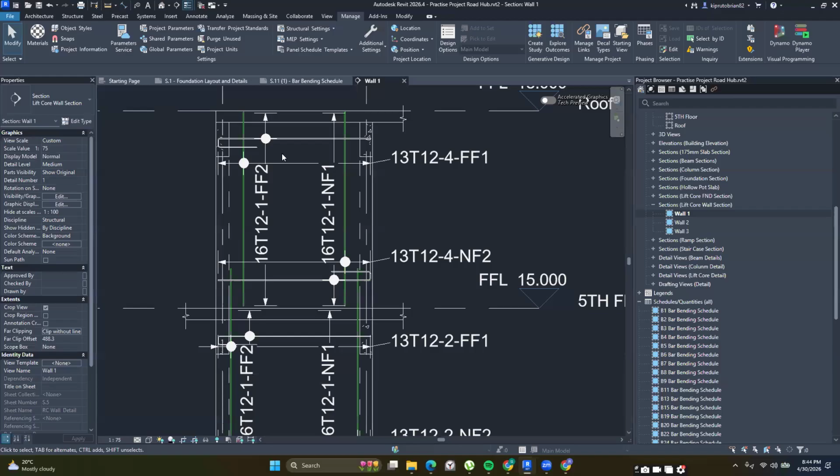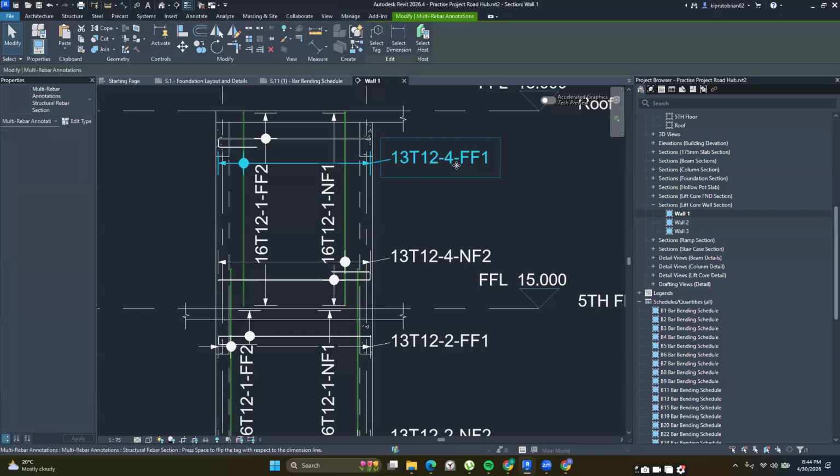So I want us to create these elements so that we can have them preset in the software, so that when you are creating your tag, when you are creating your dimension style for this tag, you can have multiple dots. By default, you're going to have the 2 and the 3 millimeter dots, but I'm going to show you how you can create even a 1 millimeter diameter dot so that you can have them in your